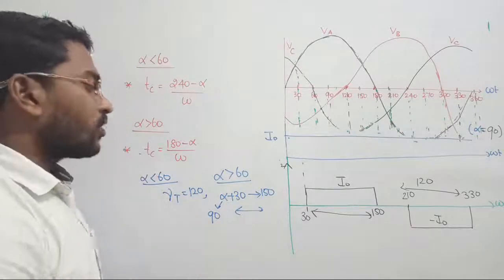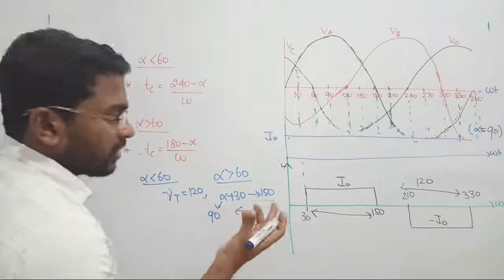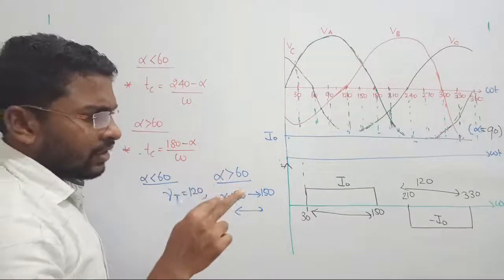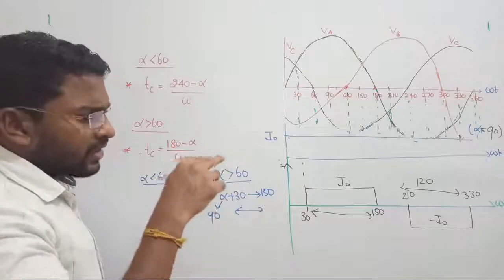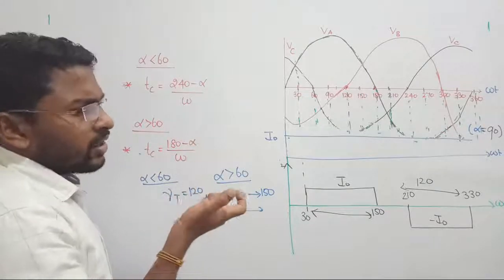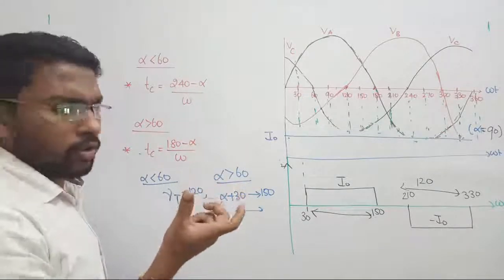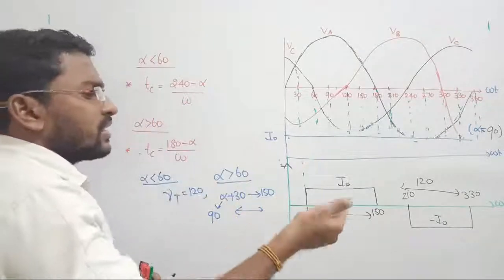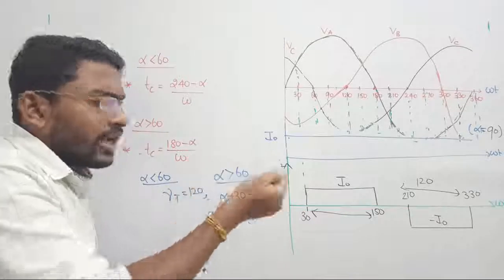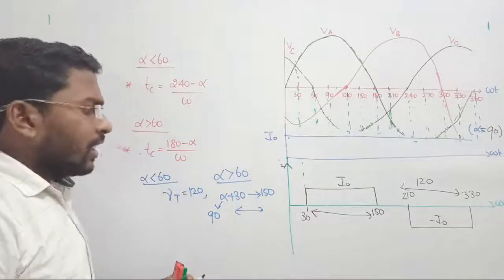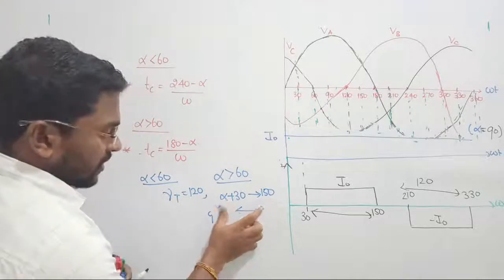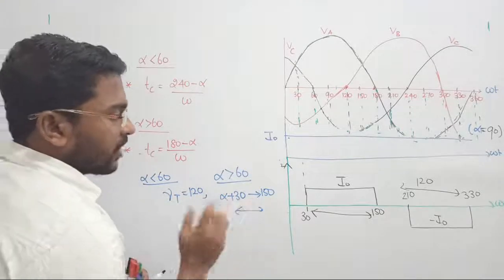So the conclusion is, when I am looking at the thyristor, at the end the conduction will come in two things. That is continuous. But if you take only T6, two are in parallel. First 60 degree you can see the thyristor conduction, and in the next 60 degree also you can observe the conduction period of the thyristor. If I select the first thyristor, it will produce its conduction from alpha plus 30 to 150.